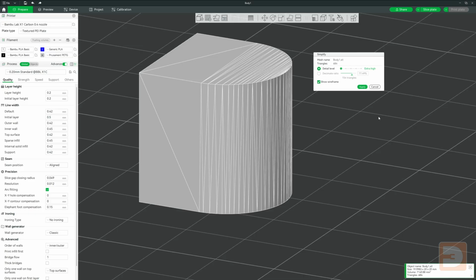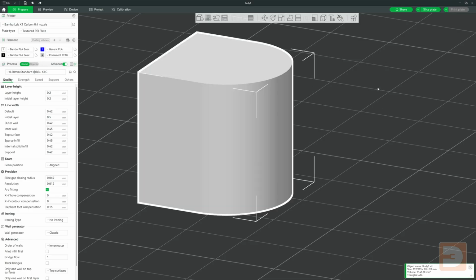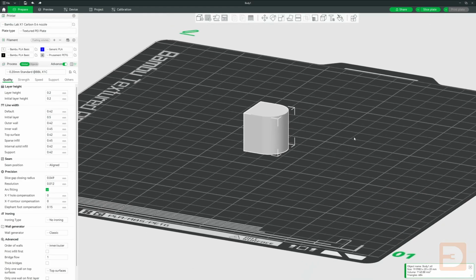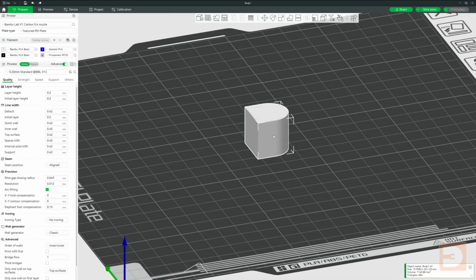This requires printers recognizing G2 and G3 moves, which most new printers do, and then it creates a toolpath specifically following this new genuinely curved line. It means that even though the curves in your STL are made of a series of flat shapes, the final print will be a true curved line.